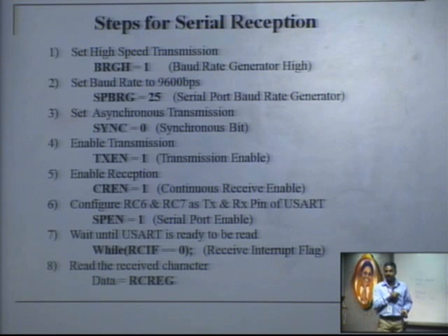So here what you should do is read the data from RCREG and give it to the work register. So MOVF RCREG, 0. That means you are reading from RCREG and writing into W.